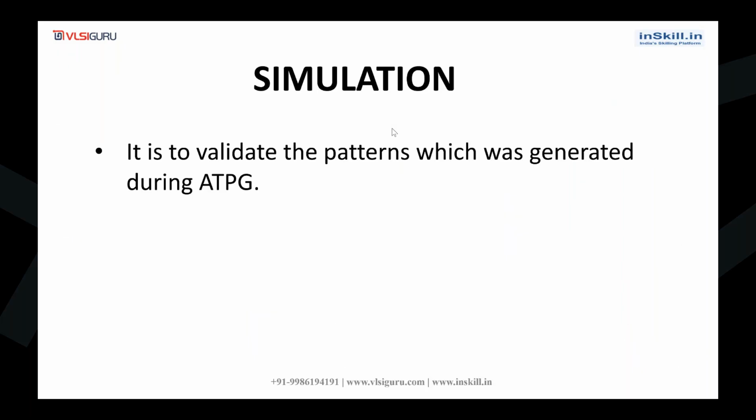Simulation means it is actually to validate the patterns which were generated during ATPG. Which means before delivering the patterns generated during ATPG to test the chip after manufacturing, we need to validate once whether proper patterns are generated or not. So that is what is called as simulation.